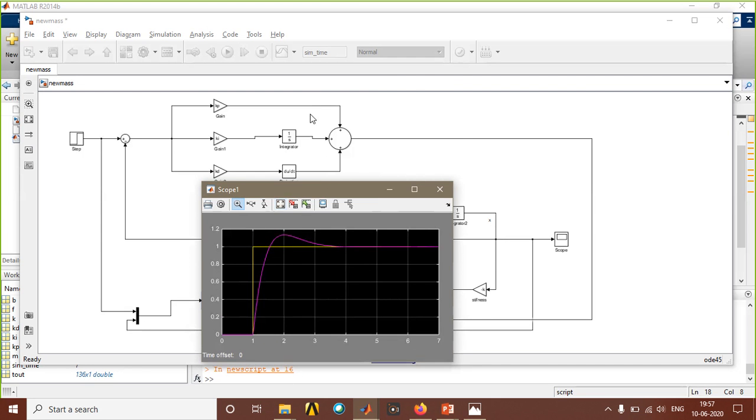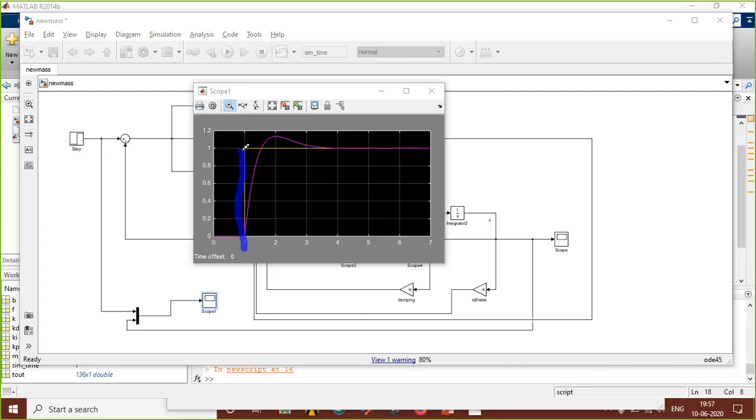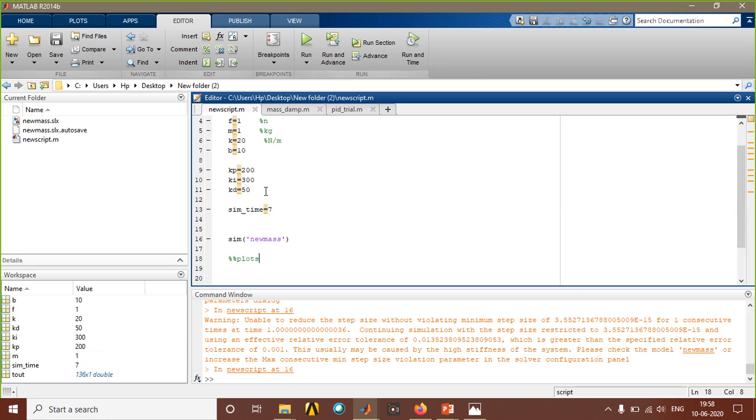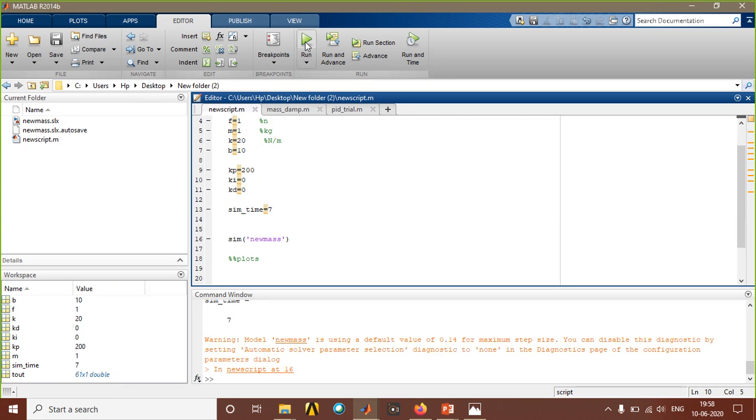The small mistake, okay? So when you see from this graph, at time 1 second, the force is getting stepped up and the force is acting on our system, okay? So what happens is, our system is getting displaced, overshooting, going up and coming down, getting settled, okay? So now I'll show you one thing, okay? In order to verify that, I tuned some of the things. What happens if you put only your proportional term, just run it. You witnessed what happened if you include present, past and future error. My system is so smooth.